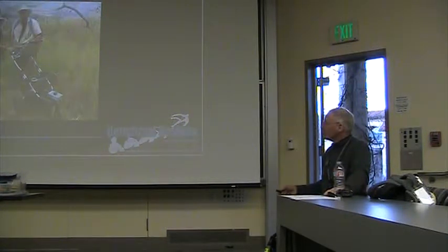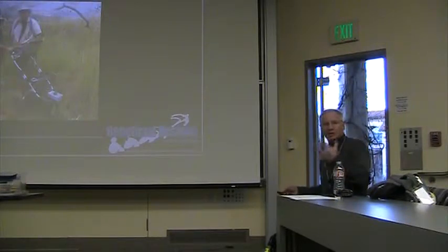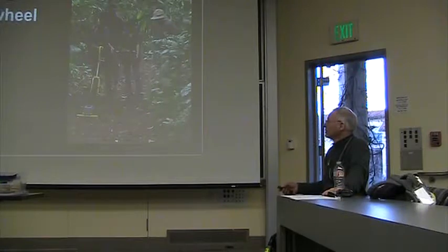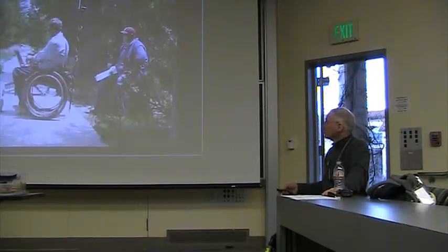And then we've created a high efficiency way to do this. It's sort of like a jogging stroller. It's actually a gun cart that's been converted. We have a sensor box there that measures the grade and cross slope, and a GPS, camera, and laptop, and we roll it down the trail and we measure the conditions along the trail systematically. We have a roller wheel version for narrow trails where you just set it down and roll it along on the wheel.